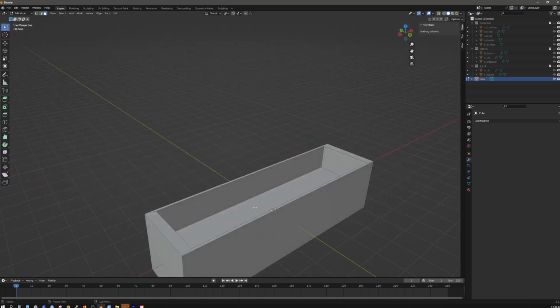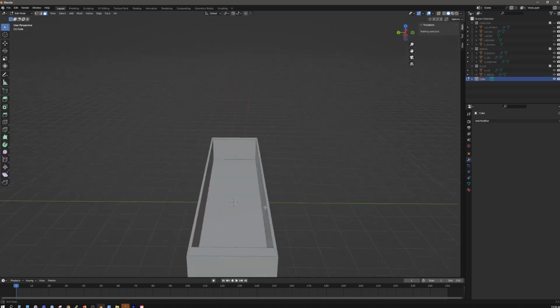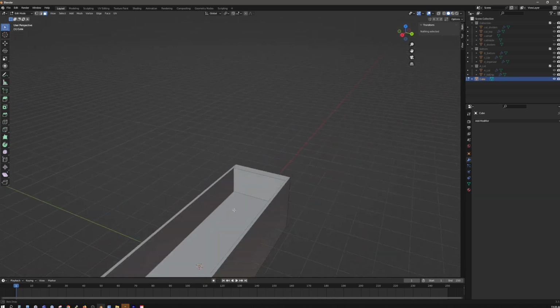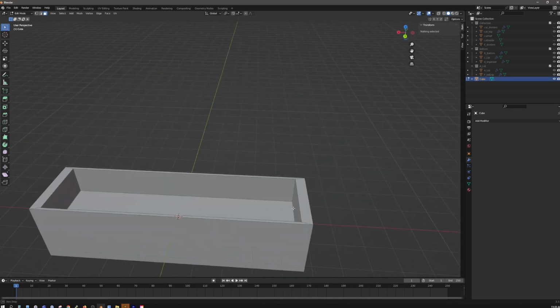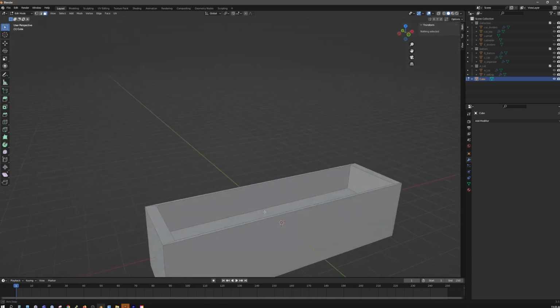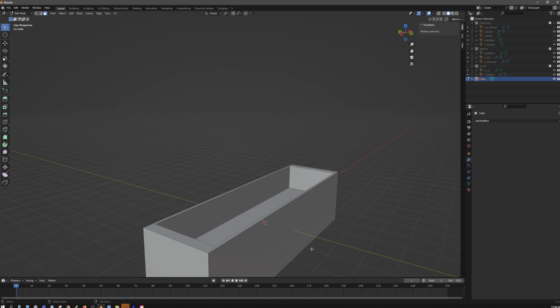With this technique, I've cut the object and basically destroyed any chances of editing it back to its original or starting fresh. So that's the reason why I don't like using loop cuts or anything like that that destroys the mesh of any kind. I like to keep things editable and my options open.